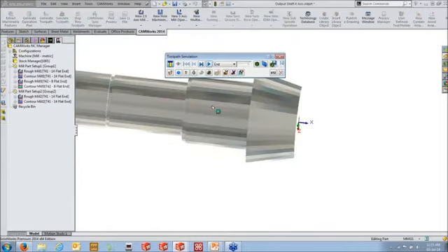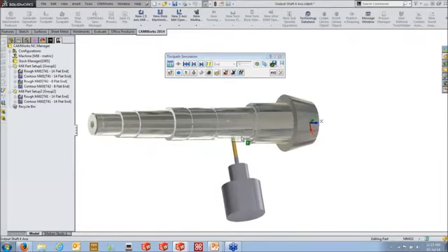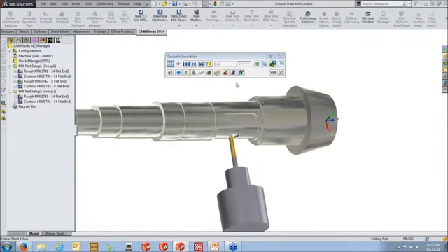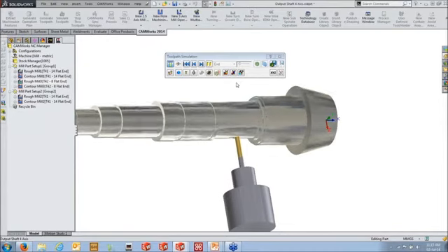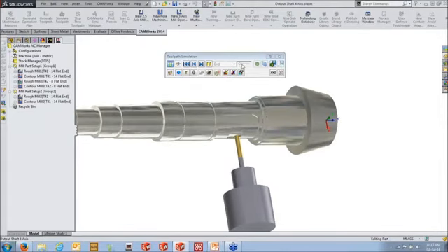And you'll be able to see those in the simulation. So if we simulate this, you should see, if we slow it down right here, it's rotating the geometry there. So we can get a good idea of what that toolpath will look like, and what the finish will look like in here as well.